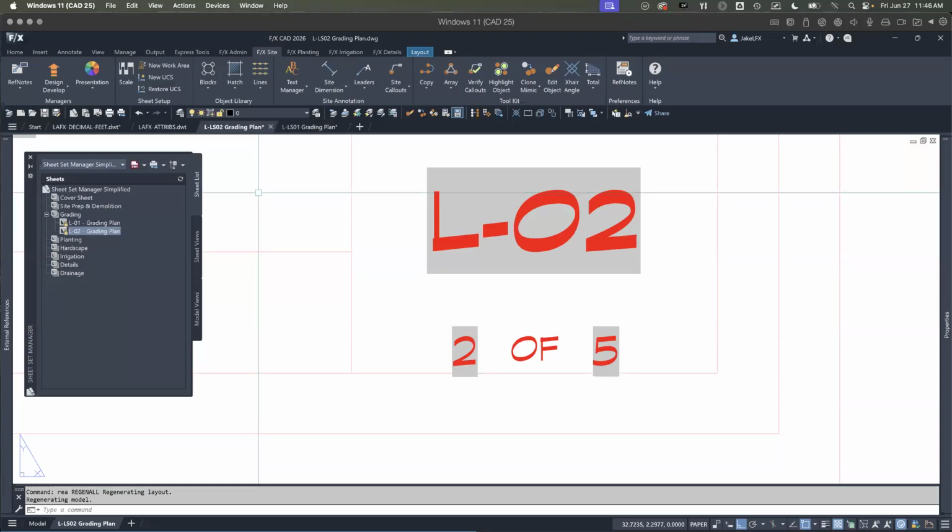So the amount of times that we've seen corruption basically decimate projects, which is what can happen. Corruption's easier to build up in a drawing with multiple layouts, and then when it does, you have to redraw all of those layouts, as opposed to if all of your layouts and working drawings are in separate files. They're easier to contain the infections to only some of them. You catch the problem before it gets too bad across all of them. That means less work to clean up, and you only have to redo the sheets that got hit really bad, which means maybe you have to redo one sheet instead of every sheet in your entire drawing package.